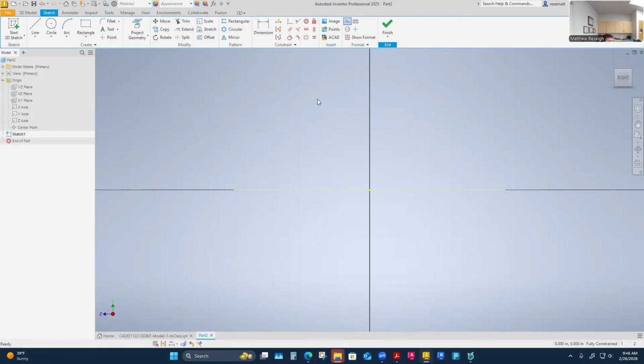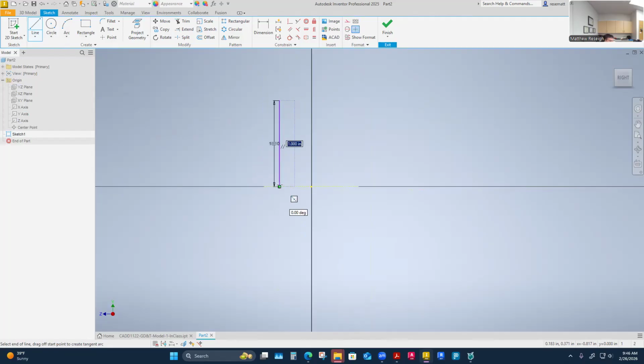You could use it as part of your sketch though, but I think I'll still draw a full solid, meaning that I'm just going to use lines, but now I'm going to be able to just snap them to here because that's my axis. So I'm only going to come up here. This is 1 inch because it's 2 inches overall. And so maybe I'll draw this with my dimensional inputs and I'll have to redimension it later.